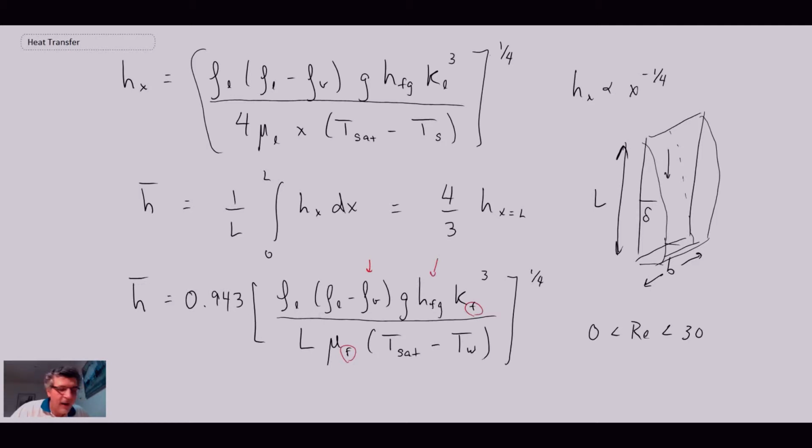The other thing I mentioned is that for this heat of vaporization that we see here and here, Nusselt actually came up with a correction. When you do your calculations, use the corrected value. Do not use this value of hfg.